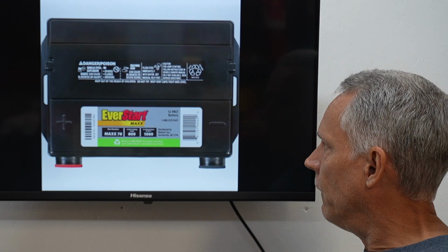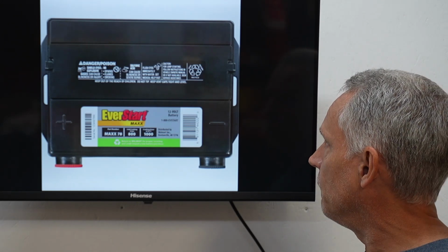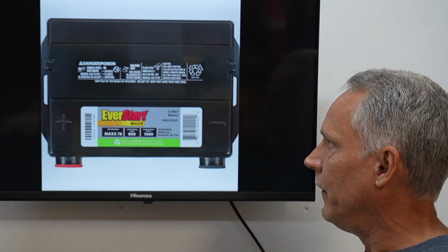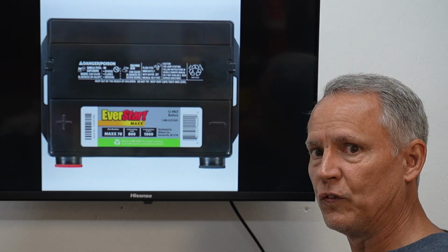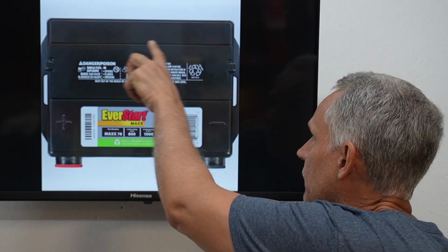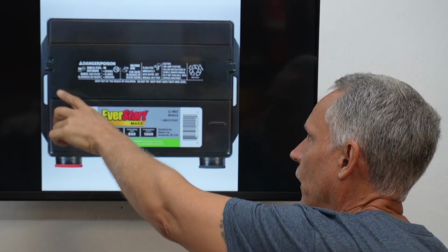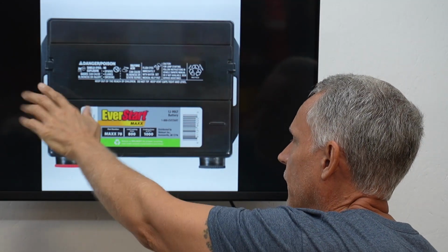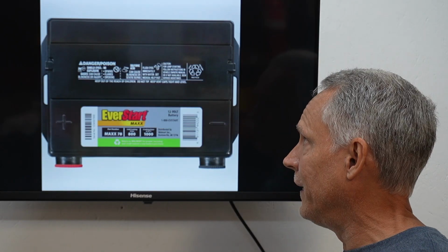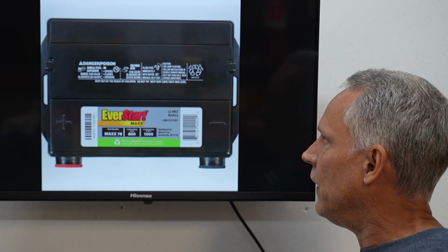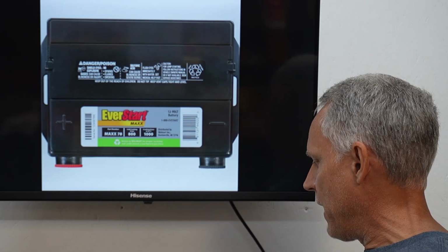So here, for example, this is a flooded lead acid battery, liquid electrolyte with a sealed top. It's not an SLA sealed lead acid battery, but it is advertised as maintenance free. And this top right here, that's actually a cap and a vent, both. These are vent ports, one there and one there. That might be able to be removed to access the electrolyte. I'm not sure. You might damage the battery if you tried. But this is a sealed, maintenance-free, flooded lead acid battery.